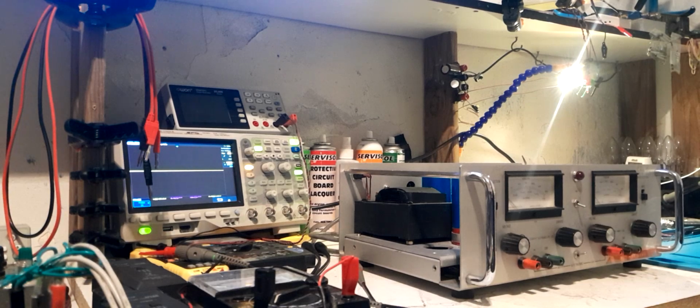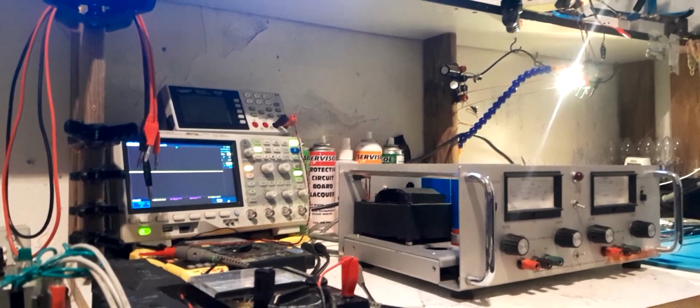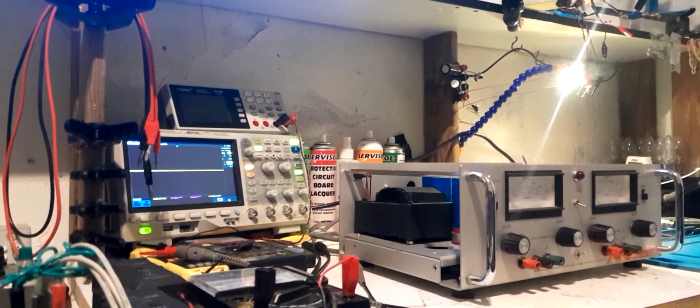The other thing I'm probably going to do at the end, I've been thinking about it, those little 10 nanofarad capacitors that are across the rails. In the old days, people used to go by, I don't know if it's so much theory, because capacitors now have so much lower ESR and better frequency characteristics with all the different types of capacitors we make now, that back in the old days you'd get say 1,000 microfarad or 100 microfarad, and you'd put that in parallel like an electrolytic.